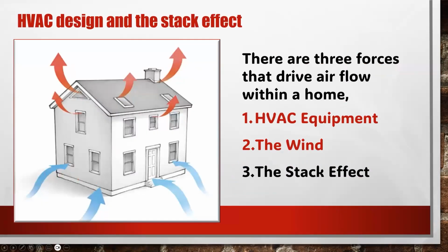So a typical house, there are 3 main forces that drive airflow, air movement within a home. Number 1, of course, is your HVAC equipment. Number 2, and surprisingly, not many people take this into account either, the wind. On a very windy day, we could have increased infiltration due to the pressure differences that are created from the windward side to the leeward side of a home. And the thing that we're going to talk about today, the stack effect, also known as the chimney effect.